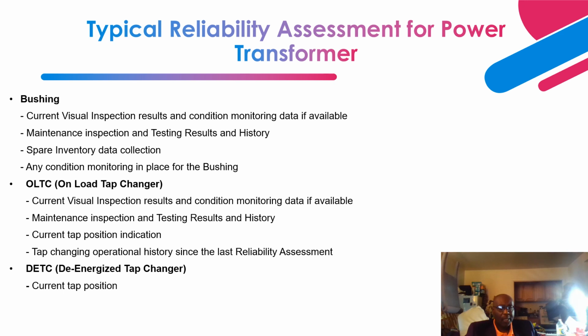Next, as I show you what should be on your inspection check sheet that you are going to use to perform your field data collection. I've made mention in the previous slide what data you need to collect from the nameplate of the transformer. So the goal is after you collect all this, you check that information with the OEM construction manual to see if what is there is what matches on the nameplate.